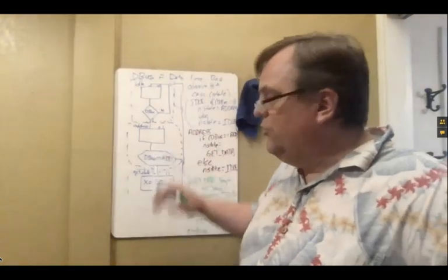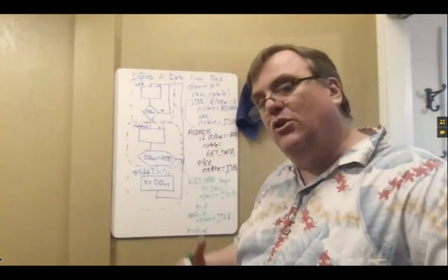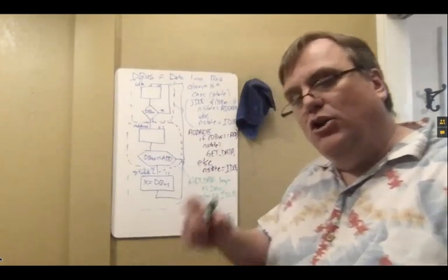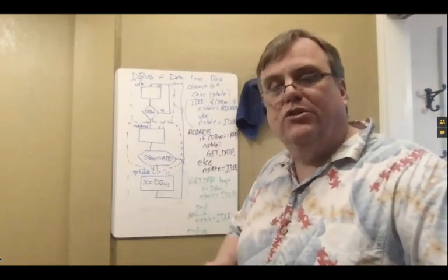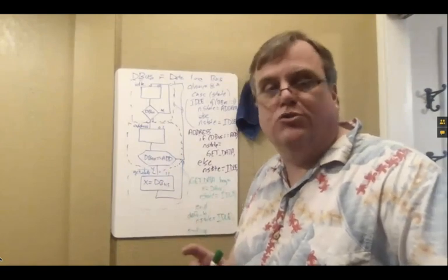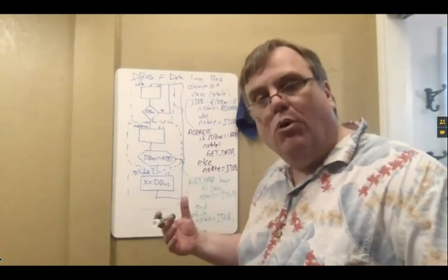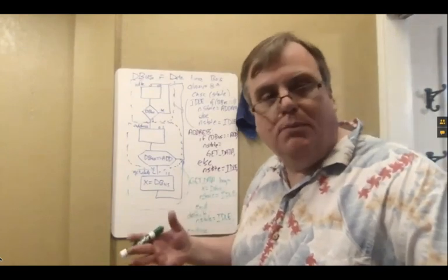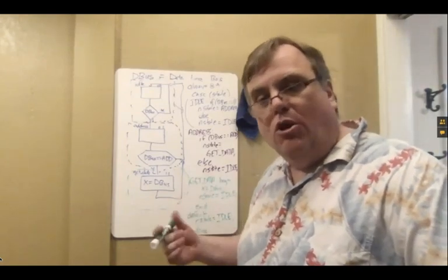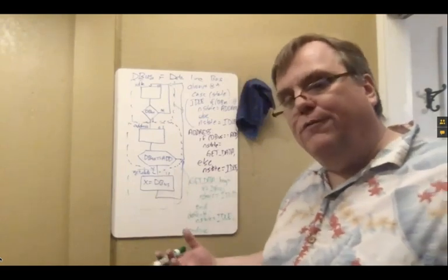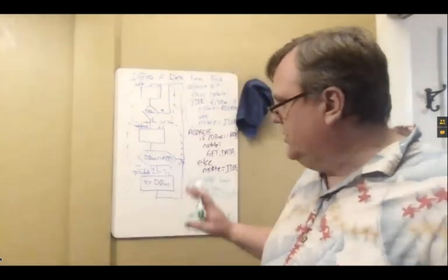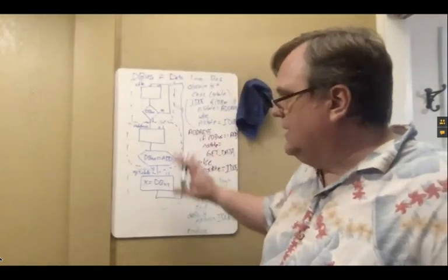If you slow the speed down on the system, it slows the clock down. Longer pulses that are sent out tend to be more noise resilient, so you're more likely to get a good signal. So if you've got a clock bus, which a lot of these are, slowing it down allows it to travel a little further and be a little more noise resilient. So that is another possibility you could do.